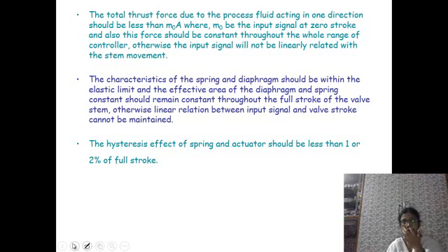The total thrust force due to the process fluid acting in one direction should be less than m0a, where m0 is, as mentioned earlier, the controller output or input signal at zero stroke condition, and a is the diaphragm area. Also this force should be constant throughout the whole range of the controller.